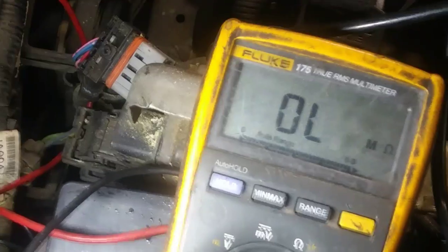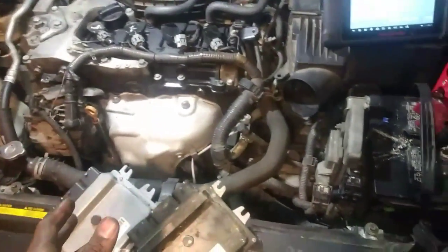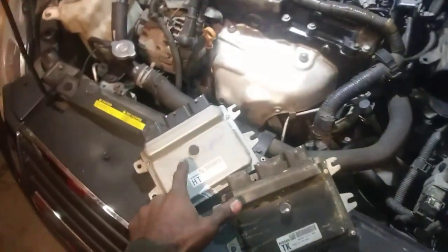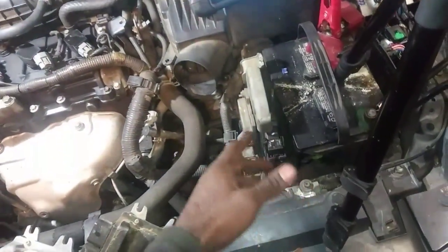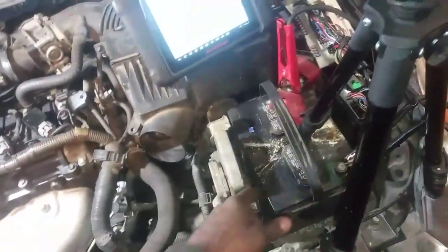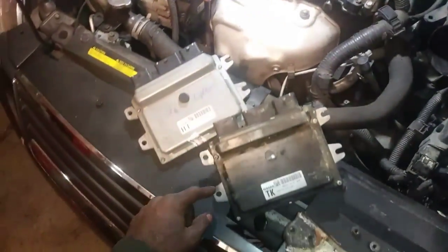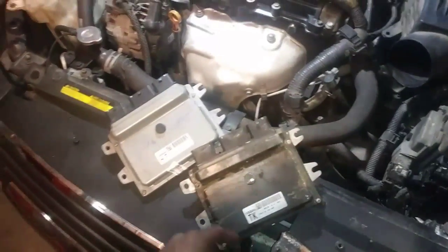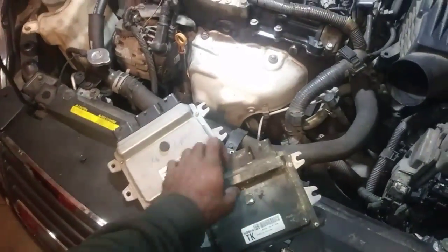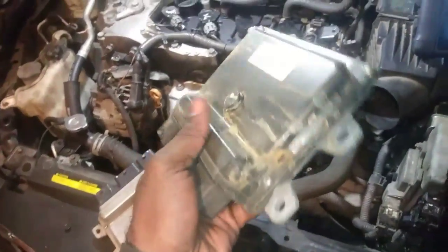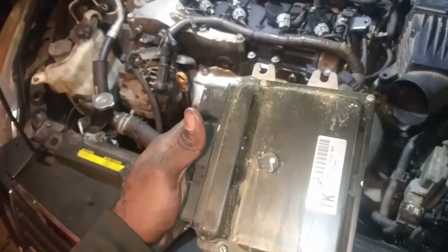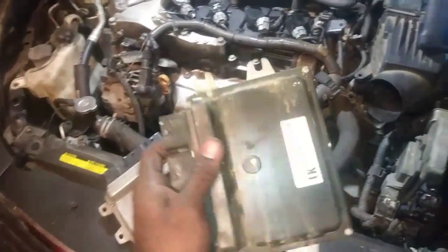Let's find a computer. All right, several hours later, I went to the junkyard. I had some other things I had to work on, but I wound up getting 2 computers. This is one of them, and the other one is in there now. Very simple replacement. Just pull the battery out and 2 10mm fasteners holding that in there, right here and catty corner to it. Here's the old one. I got one out of a 07 and an 09, I want to say.